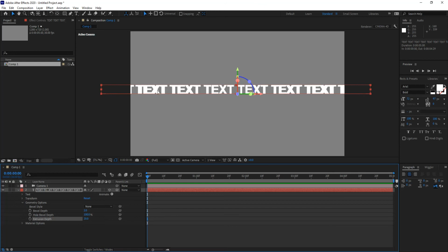And the reason why you don't see any depth is because there's no light in this particular composition. So that's the tip. Anytime that you want to create extrusion, you need to have light in order to illuminate the actual elements in the 3D environment. Because if you don't, the program basically reads no lights, therefore everything has to be illuminated equally, and therefore you don't see the depth in the areas that you have actually created that extrusion.